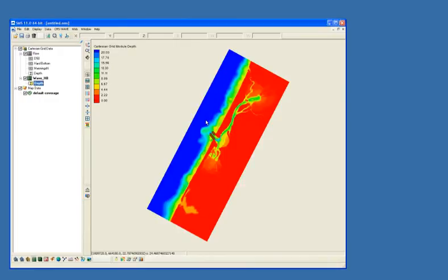You'd have wave action inside, and then wherever the wave grid stopped, you'd have nothing going on the outside, so you'd have some disparity there. So what we tend to do is we extrapolate the values that are calculated inside the wave grid and force them laterally some distance. You can specify what that distance is, or you can let CMS choose that automatically.